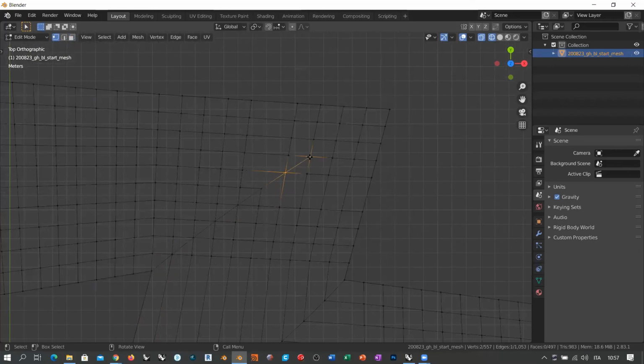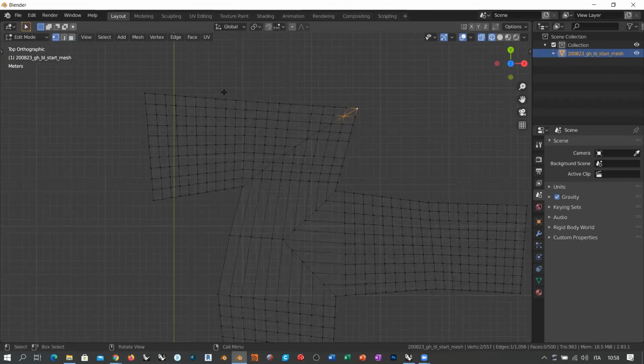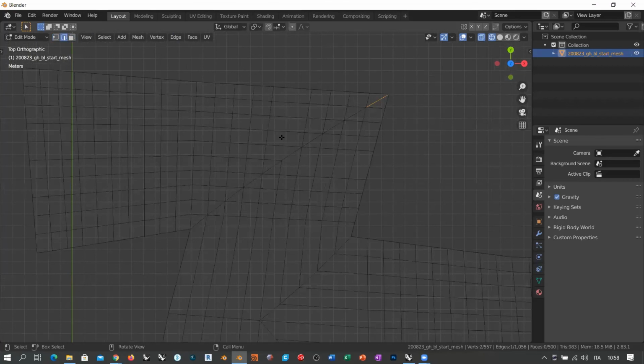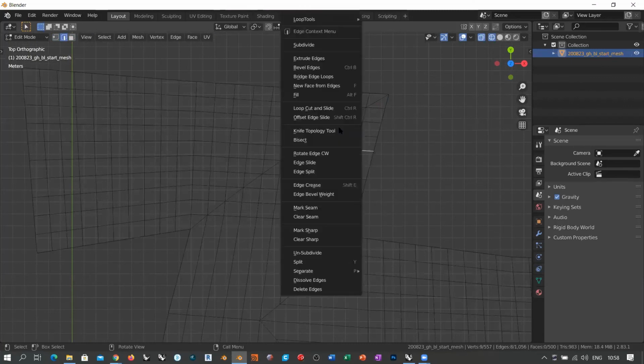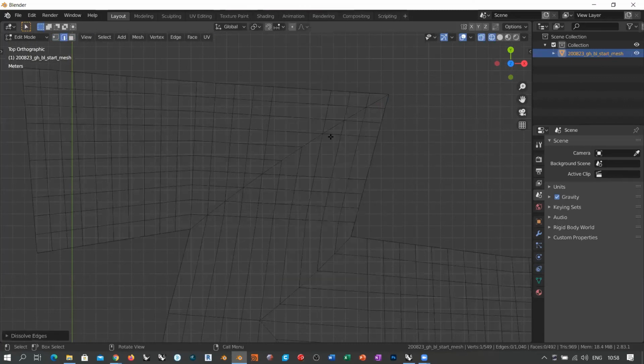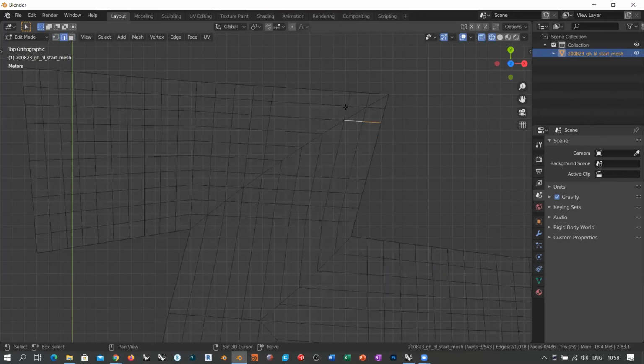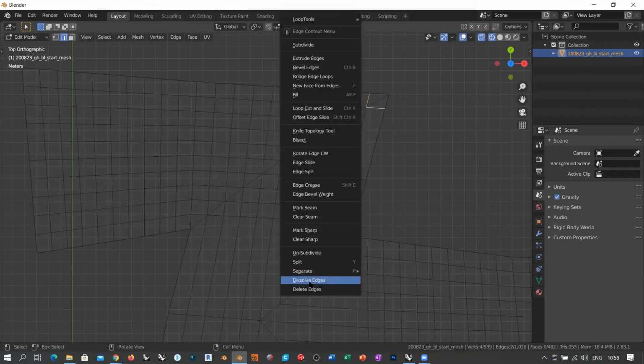And we also need on the other side something like this. So we can only just concentrate on the edge dissolve right now. So select edges, and I need this to turn left again. So I remove all these edges here, like right click, dissolve edges, and remove all these edges here. Right click, dissolve edges, all of these, dissolve edges, and these two here, dissolve edges.